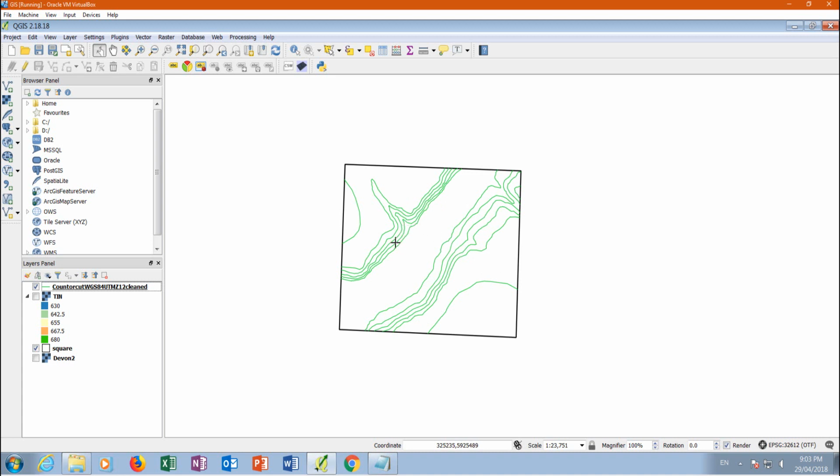It represents 1 millimeter on the map. It's 50 meters in reality, right? Then you have information just every 50 meters, more or less. If you have another kind of contour map, for example 20K, the precision of the topography is going to be better because you are going to have more contour lines, and the surface is going to be more realistic.